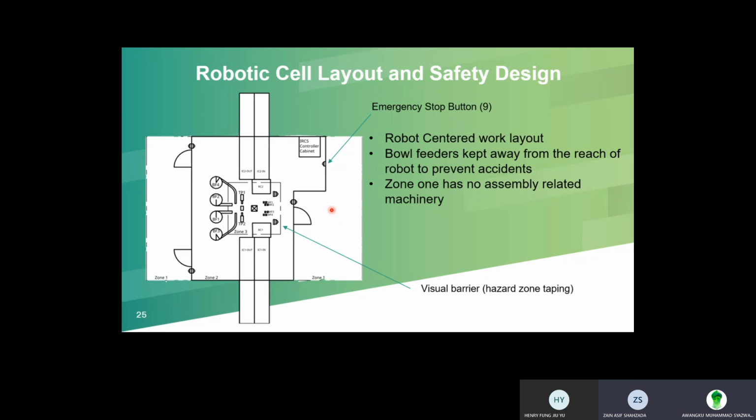I'd like to add, Zain. Yeah, the rationale of placing the emergency stop buttons is to control the movement of the robot when it's moving out of expectation. Whenever a technician is working on the IRC5 controller, if there's some unexpected movement in this area and a personnel might be affected, the emergency stop button here would be able to stop it immediately.